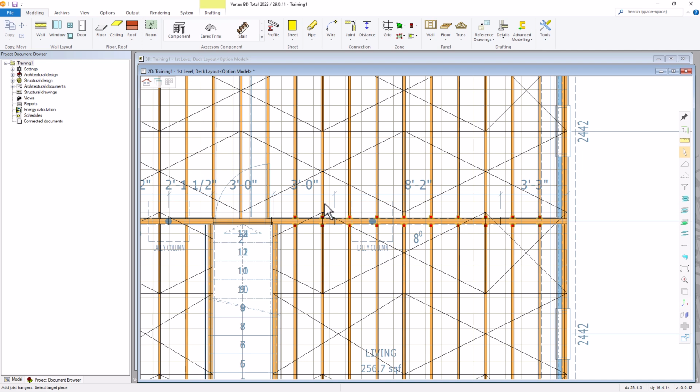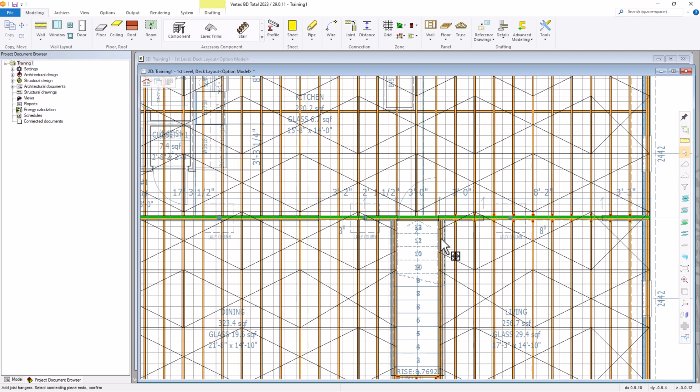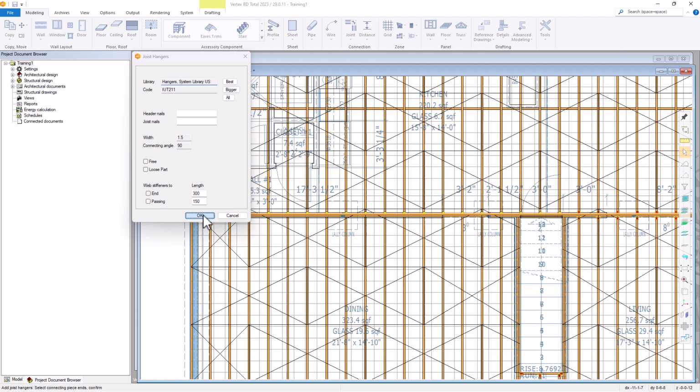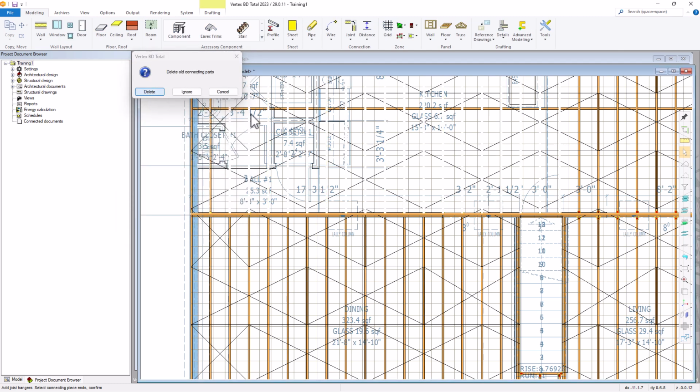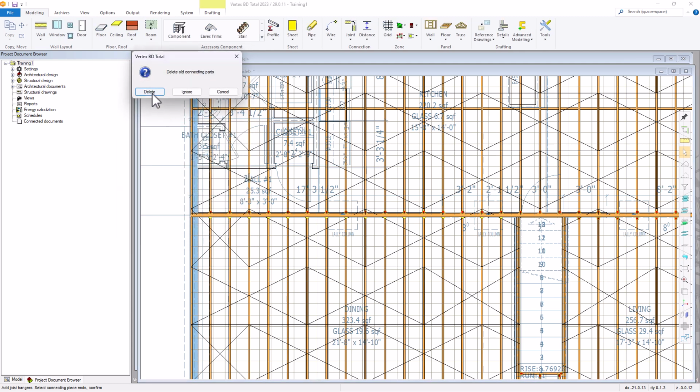Let's add hangers for the other joists. We will come back to the double joists and add hangers for those. So let's zoom out. We'll select that piece and see if we can get all of these from this point over to this end. V to confirm, and delete. Now the ply on the bottom side. Again, ignore the double joists. We'll come back to those. Crossing window, select the ends of those joists. V to confirm, delete.